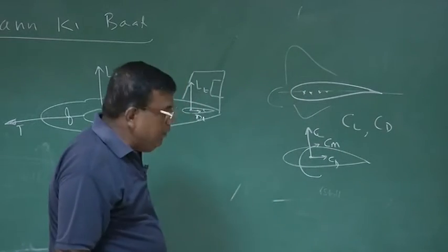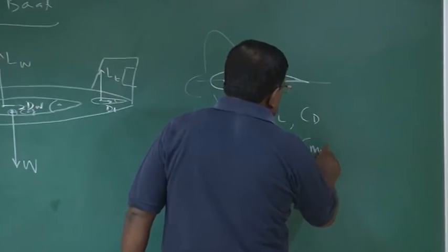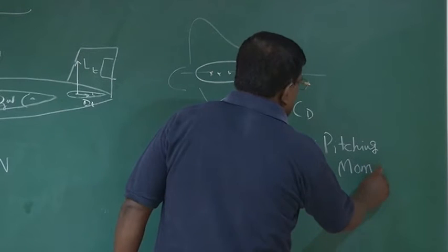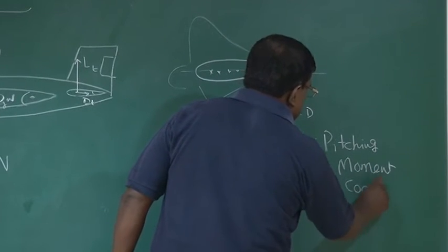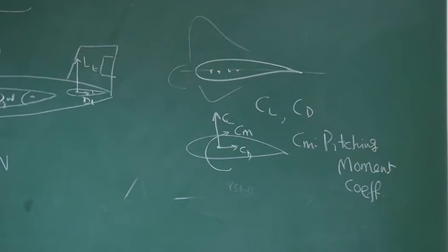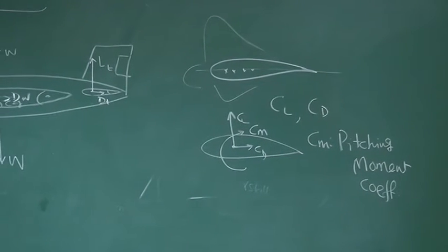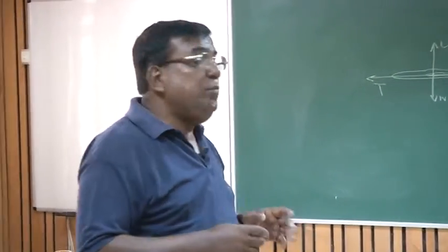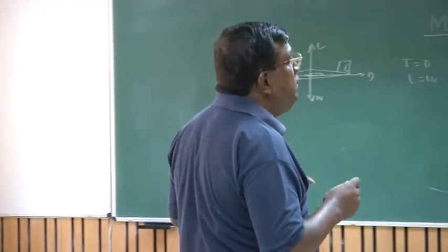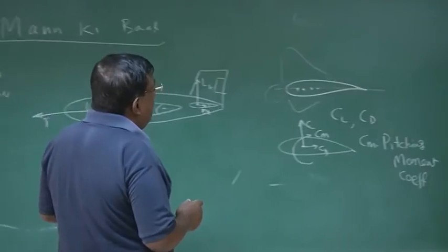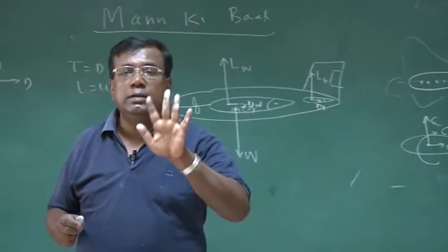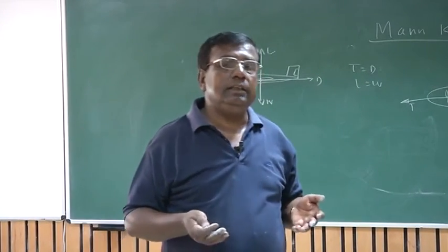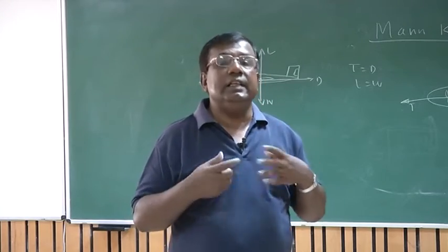We have not discussed CM, but take CM as the pitching moment coefficient. It so happens for a general aerofoil, there is a point along the chord of a thin aerofoil at which the pitching moment is independent of angle of attack. Even if the angle of attack changes, the pitching moment about that point doesn't change.